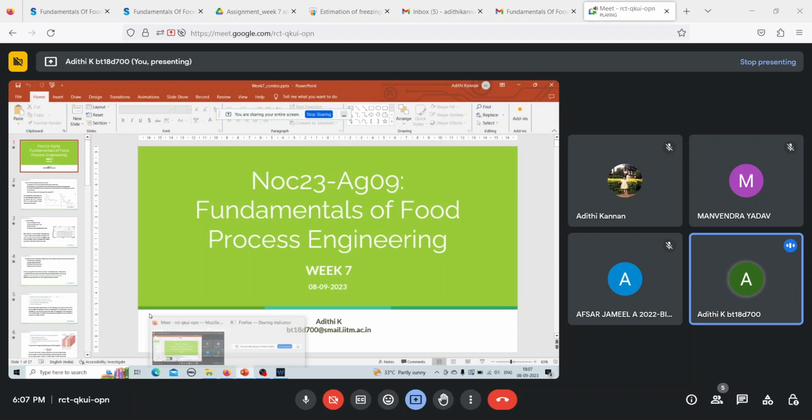Delta H1 is rho u Cpu into (Ti minus Tfm). So rho is 1000 kg per meter cube. You have Cpu as 3.6 kilojoule per kg Kelvin. I am converting kilojoules into joules, so I multiplied by 1000. So 3600 into Ti, which is 10 degrees Celsius, minus Tfm, which is minus 7.134. From there, you get delta H1 as 6.1 into 10 power 7 joules.